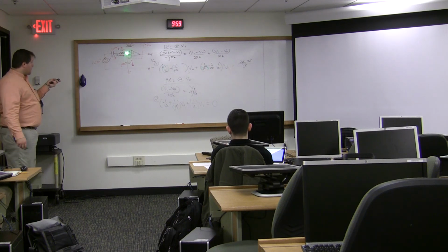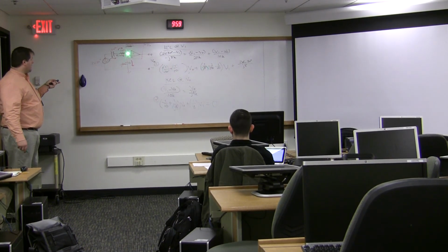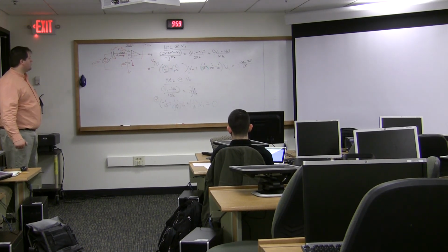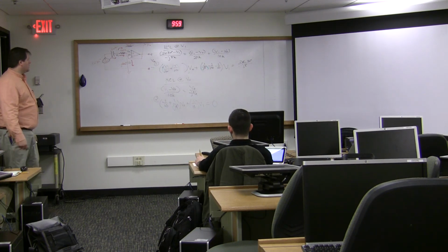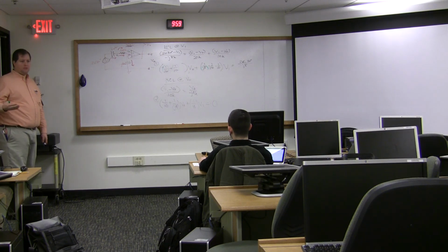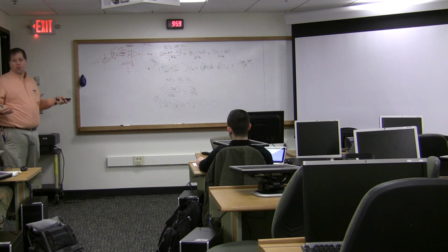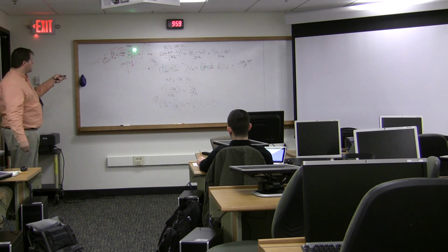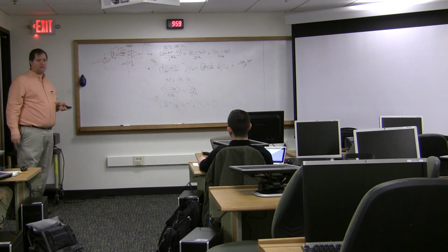So remembering to apply your golden rule that the inputs are equal, and applying KCL at the nodes, at those unknown nodes, that's the best approach that I can think of. It's also kind of handy when you're doing op-amps. You pretty much always need to do KCL at the input node. That one's pretty important, right? Even though you know it, that's one of the nodes you need to use, almost always.